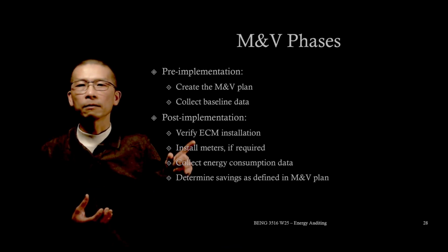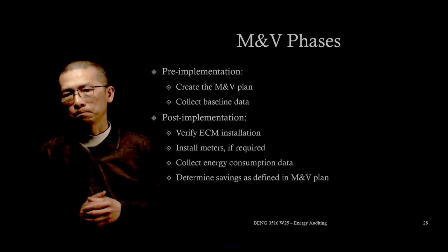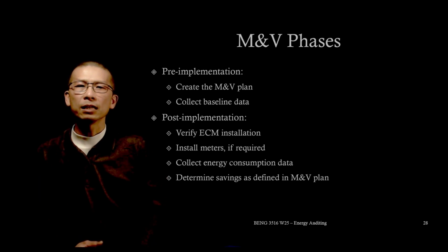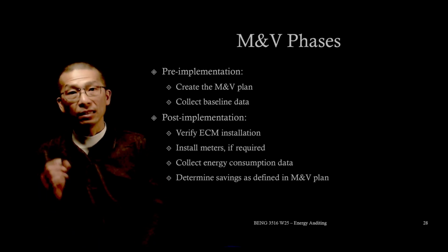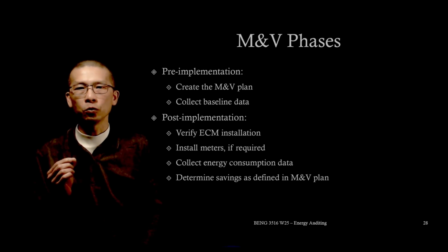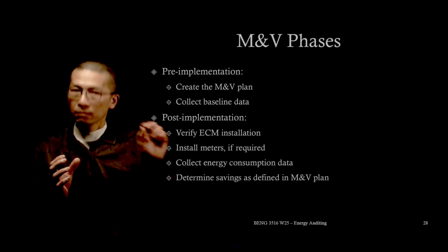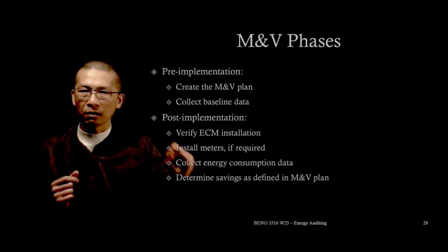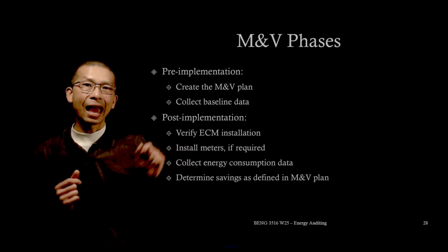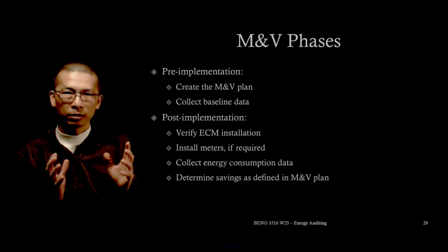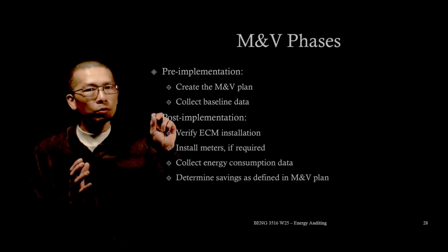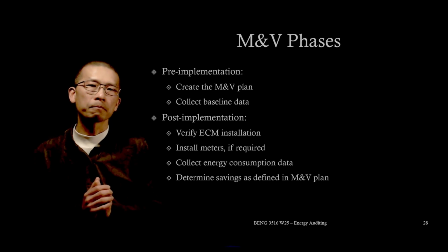Also, it can involve installing meters if required. If the M&V plan calls for detailed sub-metering to isolate individual ECM impact, then install and calibrate these meters to accurately capture energy consumption specific to each ECM.